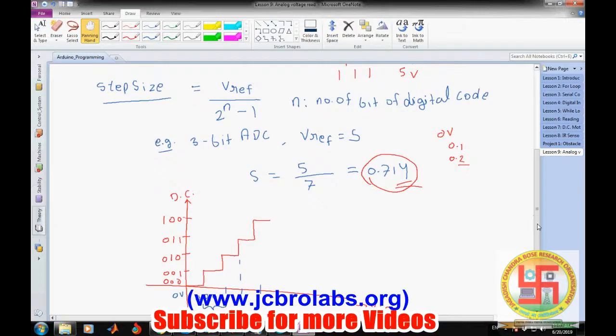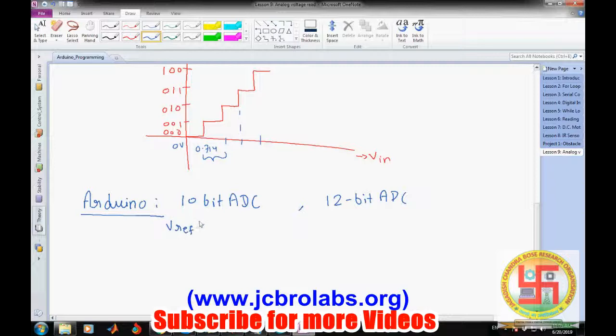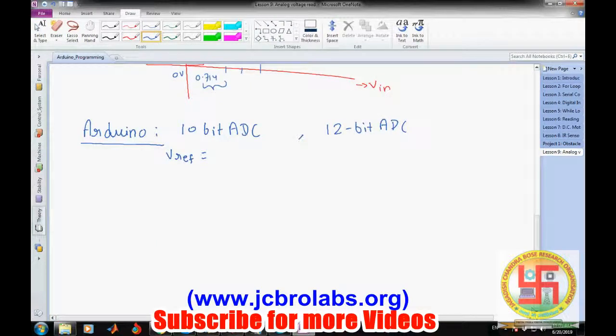So this is about the ADC and its resolution and how this step size and the number of bits relate to the digital value. Okay, so in Arduino, we have a 10-bit ADC. If you go to the data sheet of the controller which we are using, it is a 10-bit ADC. Some of the AVR microcontrollers also have a 12-bit ADC. Okay, so for a 10-bit ADC, many times V reference could be 3.3 volt or something else, but most of the time we will be using 5 volt as the reference voltage.